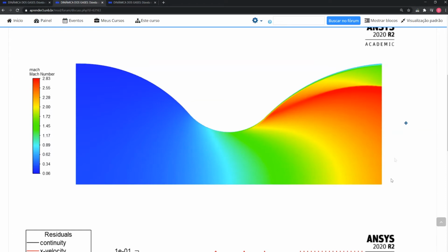You will have some difference with respect to work 1 in the region of the exit of the nozzle, because this shock wave here was not calculated analytically, right? And since there is no such calculation, at the exit points of the nozzle you will have a bigger error with respect to work one. Okay, in all other points, in the throat and in the inlet section, there should be very, very good correspondence until this moment appears, which has not been calculated in work one.